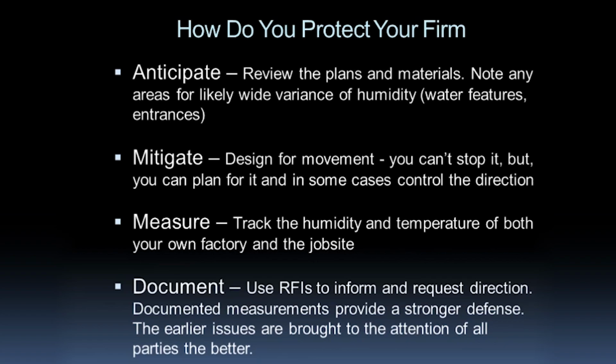But that's one thing to be aware of. I would check them just to make sure, because in those situations you can end up putting solid wood with a high moisture content up against sheet goods with a low moisture content, and then those are battling themselves along with the humidity that's there on the site. So I do recommend that you do that. How many people actually check the material that comes in with a moisture reader that they stick in that material?